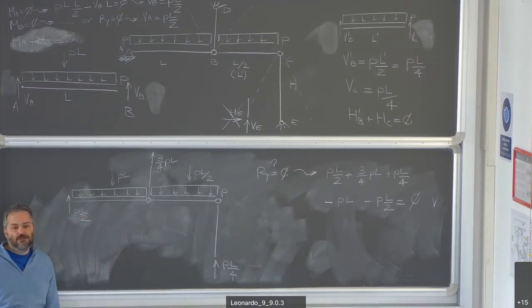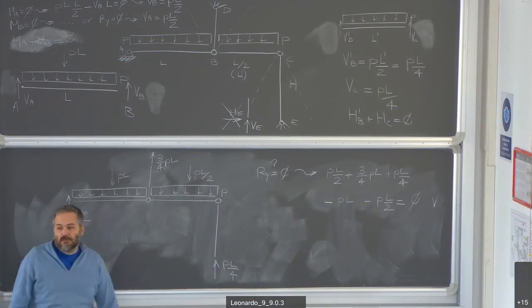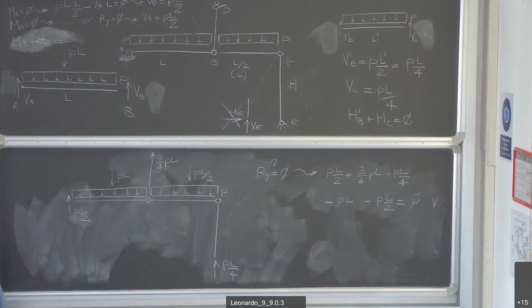Do we need another equation? Well, horizontal equilibrium is obvious. There is nothing in the horizontal direction, and there are no reaction forces in the horizontal direction. Okay? You could write a moment equilibrium. Pick a point.